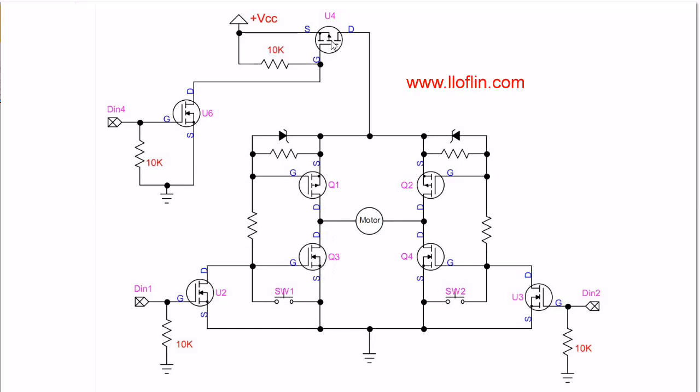So using the combination of the high-end switch and proper programming, assures that there will be no shoot-through, that the braking action will give it time to stop, because if you immediately reverse direction, with say you want to go counterclockwise and this thing is still spinning clockwise, you're going to throw a lot of current and spikes through the system. You don't want to do that.